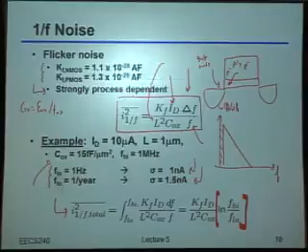Because let's just say, for example, you have a circuit that's DC coupled at its input, right? Let's say I had an amplifier or something, right? If it's just sitting there and running for 1 full year, then I'm going to integrate out to 1 full year in terms of the quote-unquote bandwidth that I'm interested in. Now, of course, the total variance of noise you'd see from time 0 all the way to time 1 year would go up, right? But really, the meta point here is that it's not going to go up by much.